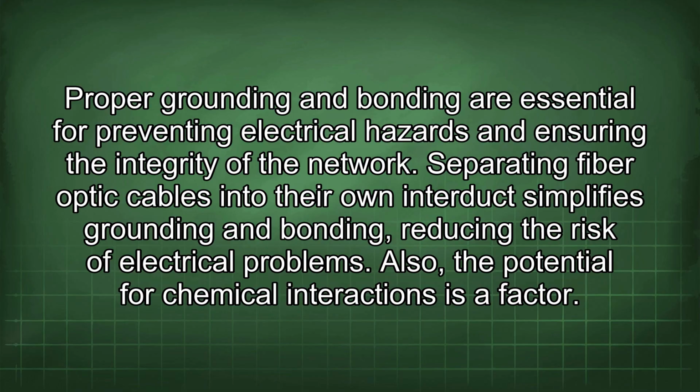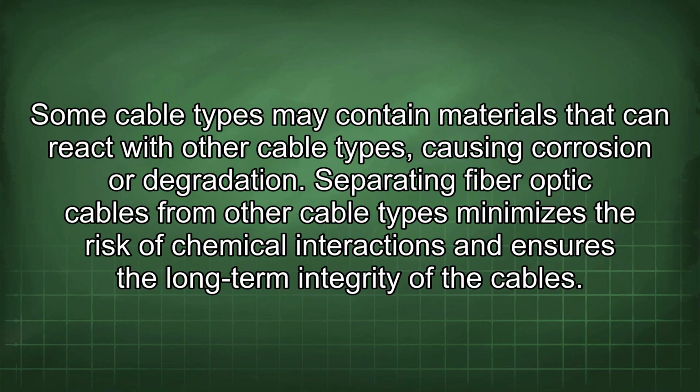Also, the potential for chemical interactions is a factor. Some cable types may contain materials that can react with other cable types, causing corrosion or degradation. Separating fiber optic cables from other cable types minimizes the risk of chemical interactions and ensures the long-term integrity of the cables.